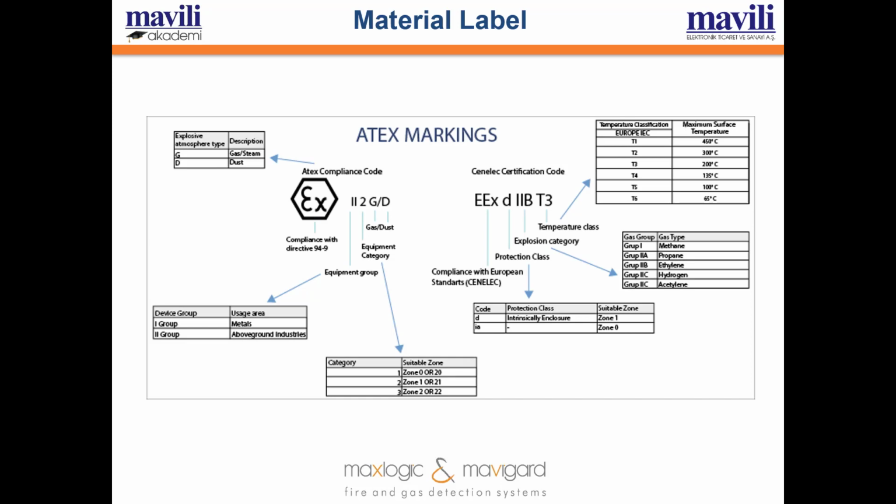Third and the last one is D-type protection. That is flame-proof enclosure. There is no need to use the Zener barrier in the D-type protection product because the D-type protected product doesn't leak out an explosion in any impact that may come from the voltage source. Thus, we can protect the explosive atmosphere directly with the D-type product.